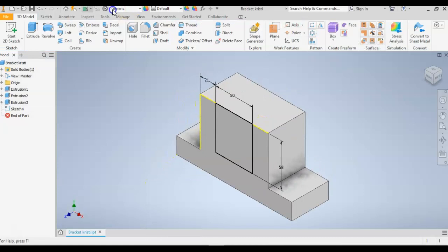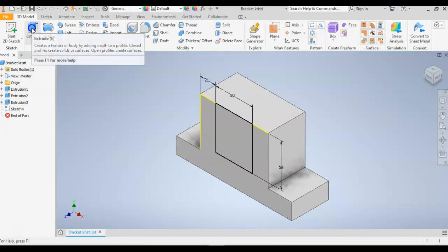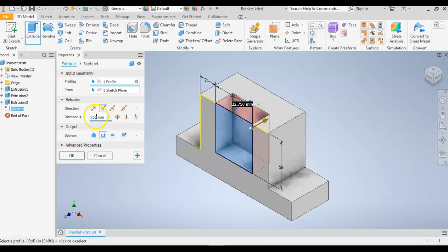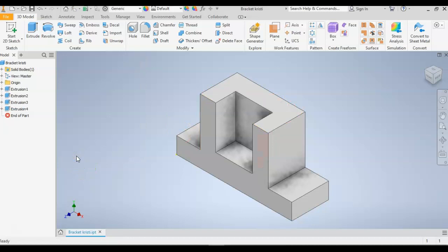Like all of our other dimensions, and all of our other shapes, we are going to extrude this shape. The default is to extrude out. Now this time I can either grab my gold triangle and slide it in, or I can come to the box over here and say, hey, I want you to go the other direction. Now I want my number to change. I want my dimension to extrude for a depth of 27. I'm going to make sure that it's going back and it's turning red, and I'm going to hit OK on my screen.